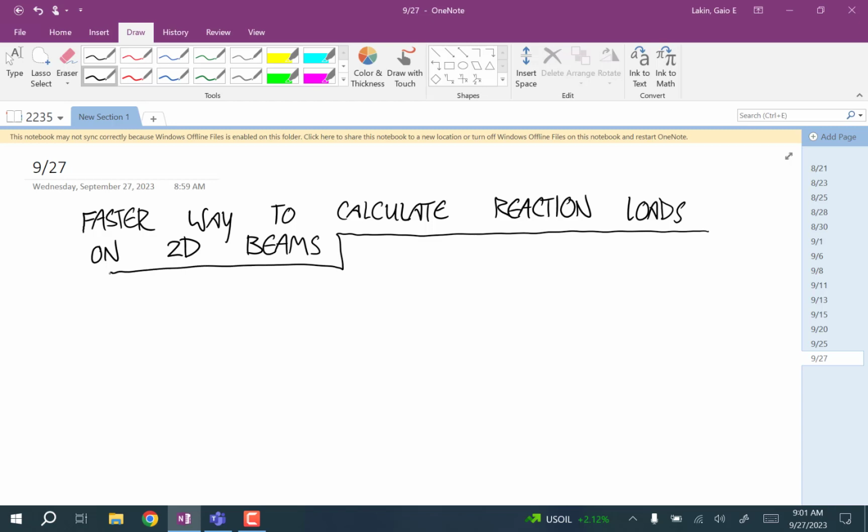And what do I mean by a beam? The part everybody would get right, if I made you guess, is that it's something a lot longer than it is wide. It's a long thing. But beams really refer to the way that it's loaded. A beam is something that has loads on it besides just axial loads along the length, either tension or compression.